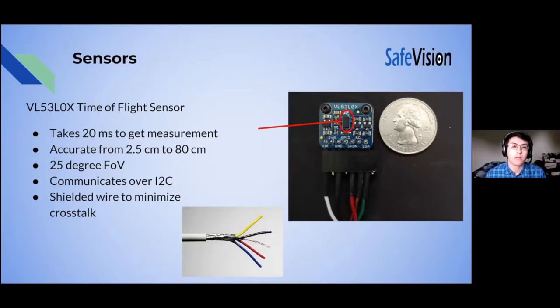For the sensors that we chose to use, we chose the VL series time-of-flight sensors made by ST Microelectronics. They are Class 1 optical sensors. That means they use infrared light to measure physical distances, thus being safe for the eyes. This is especially important for our purpose because we don't want to damage our patients' eyes during surgery.